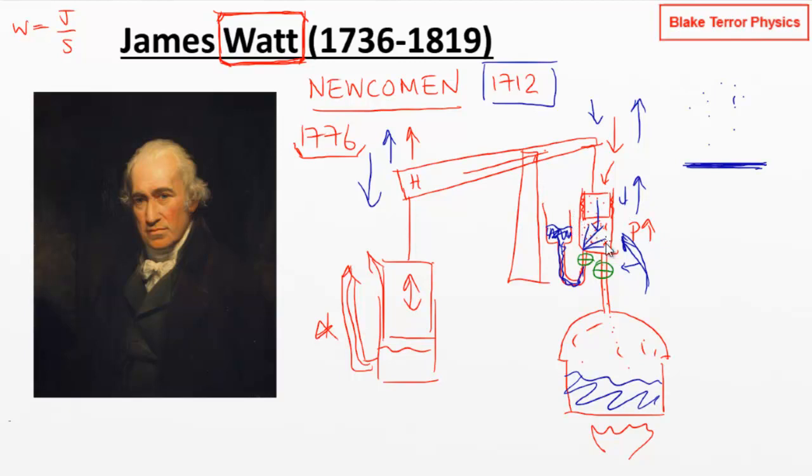So not only are you using a whole load of energy that you don't really need to use in heating the piston and then cooling it and heating it and cooling it, but all that heating and cooling of the piston is also going to put it under greater stress, so it's going to wear out quicker.